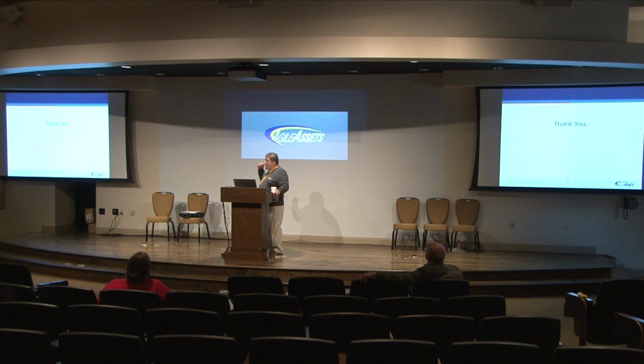When I was doing that realignment, I just picked a point here, picked a point there. By default, it was 7 decimal places. But on the other hand, when I did that realignment, it put a calibration point at both of those things. So this would solve that, in that once you rounded those things and applied updates, the ends of the realignment would be at a rounded value. So I think you're right.